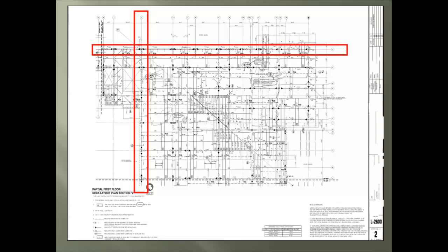We see the plan view sheet for the metal decking, and as with the design drawings, this view is like a bird flying over the project. First, the arrow shows us the sheet callout, which is the partial first floor. Then, as we have seen before, here are the grid points with numbers running one way and letters going the opposite, and where they meet is the grid point. Next is the north compass, and remember, if no compass is provided, north is always the top of the page.